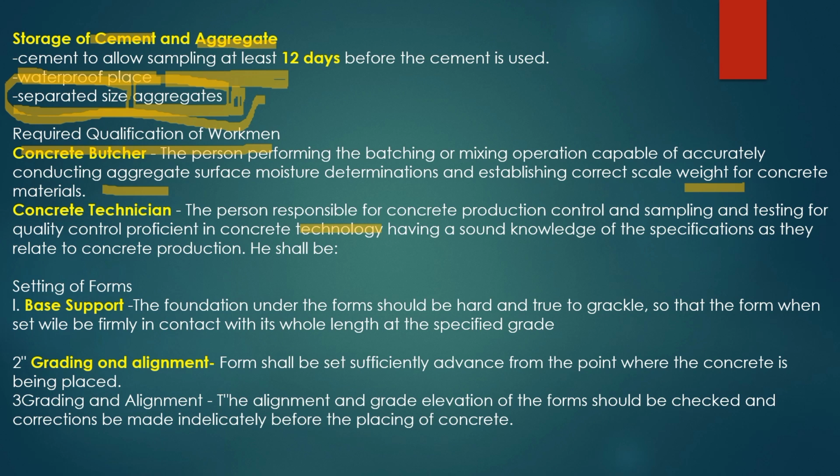To settings of forms. So number one is base support. Base support is the foundation under the form. It should be hard, true, and graded so that the form, when set, is firmly in contact with its whole length and specified grade.